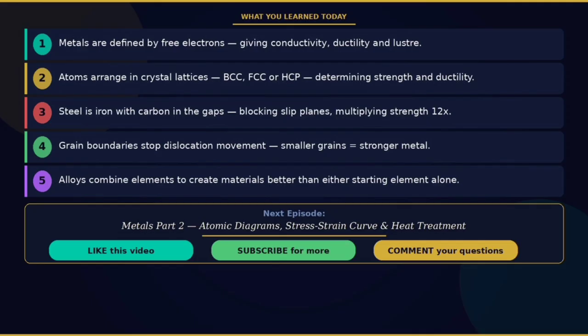Let us recap the 5 key things from today. Metals are defined by free electrons. That one feature gives them conductivity, ductility, and luster. Atoms arrange into crystal lattices, BCC, FCC, or HCP, and the structure controls how easily atoms can slip, which controls ductility and strength. Steel is iron with carbon in the interstitial gaps. That small addition blocks slip planes and multiplies strength by up to 12 times.